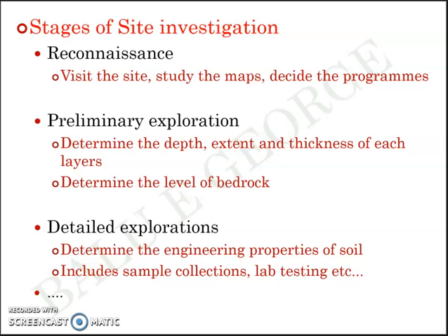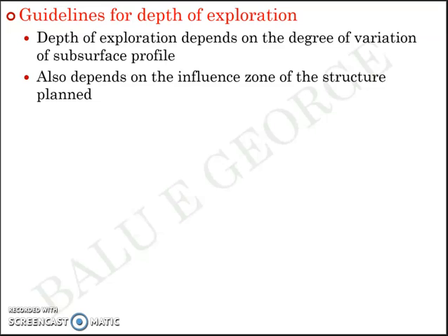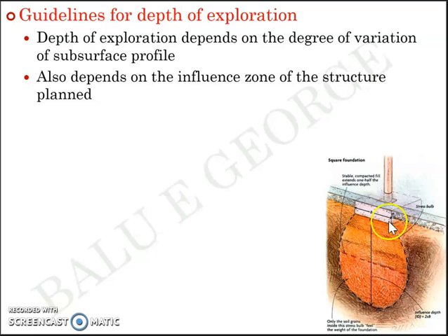Now, the guidelines for depth of exploration, which means to what depth the soil should be explored for a particular project. The depth of exploration depends on the degree of variation of the subsurface profile and also the influence zone of the structure. We had discussed what the influence zone means, the isobars, the pressure bubble, etc. So you are actually interested to arrive at the properties of the soil which is within the influence zone. And the soil which is within the influence zone is predominantly the one that governs the load carrying capacity.